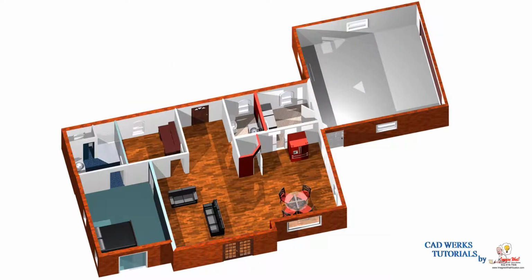On this slide you can see we just added a nice bureau. This is one that I downloaded. It was in STEP file format, so I had to blow it all apart and regroup everything and then add properties, because STEP, as I said, when you import it and try to render it, just looks like a gray blob. So to take advantage of the TurboCAD rendering properties, I had to explode it a little bit and put things into groups.